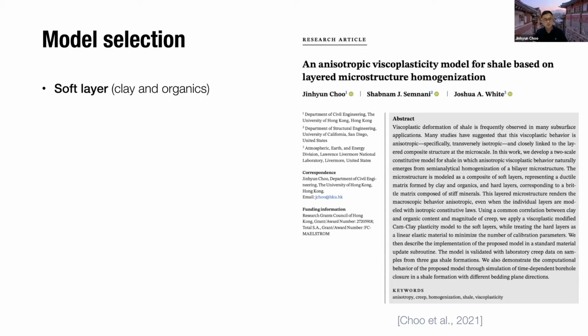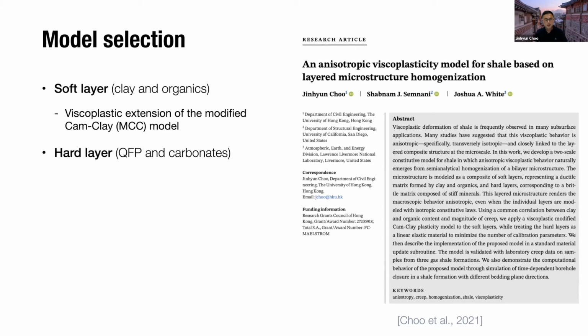For the soft layer comprised of clay and organics, we introduced a viscoplastic model, because this soft layer is mainly responsible for the viscoplastic behavior. Whereas for the hard layer composed of QFP and carbonates, we simply use linear elasticity because there's no viscoplastic deformation in these materials. Please note that one can use different models for these layers, and this is just our choice. But we will show that this choice will reproduce real behavior.